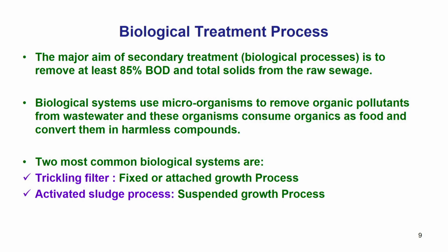The sludge wastage also happens. There is a cycle time used for various activities: fill, then react, then settle, and then decanting, and then there is some idle time. I am not discussing those processes.